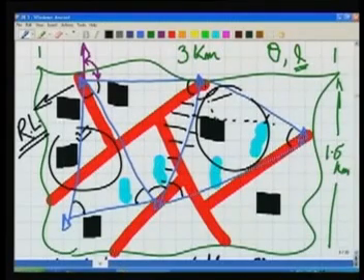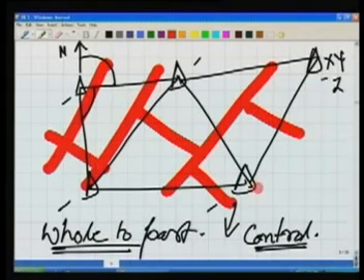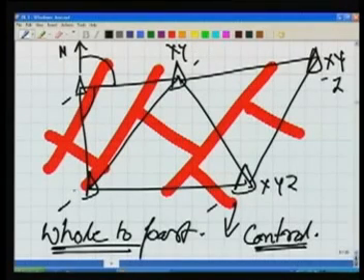That is the height of this point from the mean sea level. Once I have measured the vertical angles and the horizontal angles, I know this length, which is computed, as well as the vertical angle here. So I can compute the RL of this point also. So basically we are computing the x, y, z of all the points. So it's a full control.